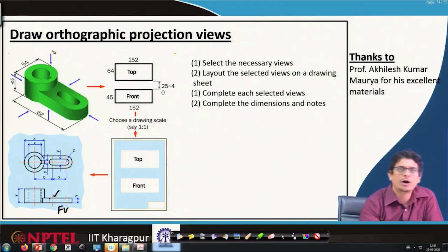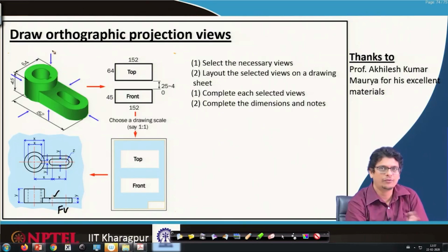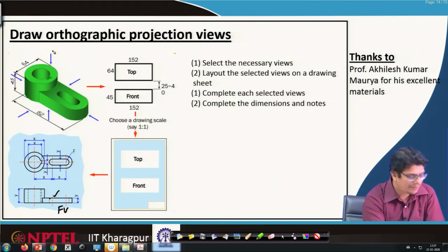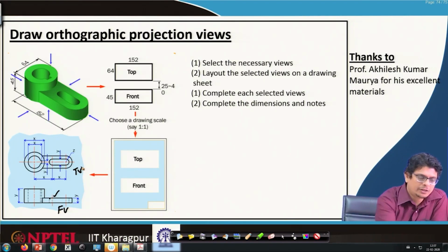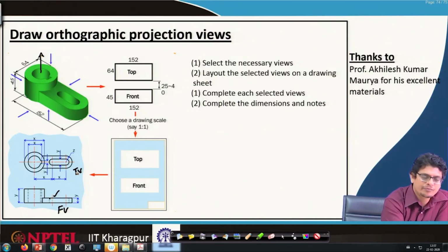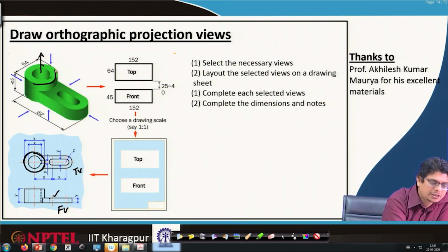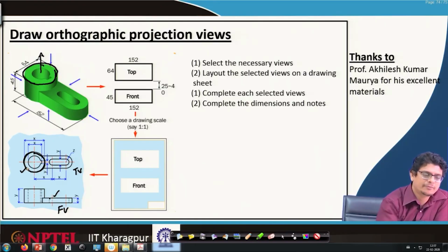Now, project that onto that glass box plane and flip that plane, then we will have a top view. Now, if we are looking at the projection onto the top one, unfolding it, it comes as the top view there. This entire circle comes out like a circle there. So, the cylinder top portion looks like this one, that one is this.